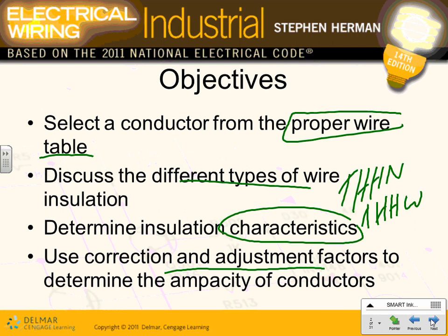Here's the rule. When you guys become estimators and project managers, always put the feeders in separate conduits. When you have a feeder, the worst thing that could happen to you, Darren, is you grab two feeders, 200 amp each, and put them in the same conduit. Not a good idea. If you have a feeder, use dedicated conduits.